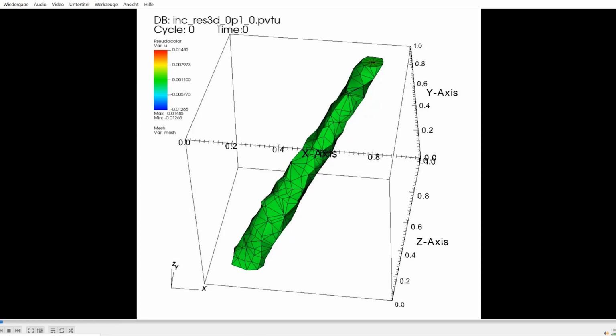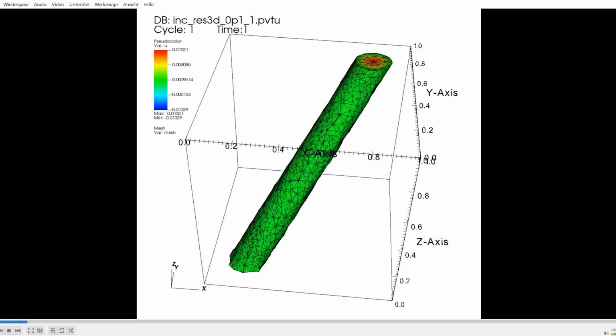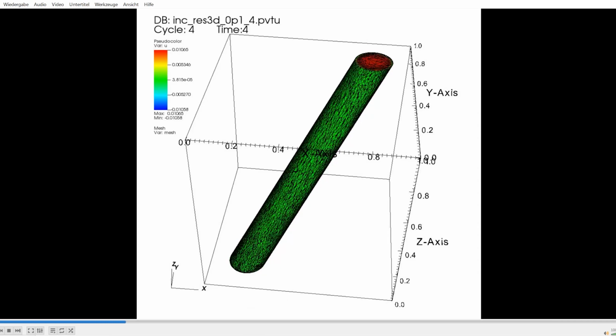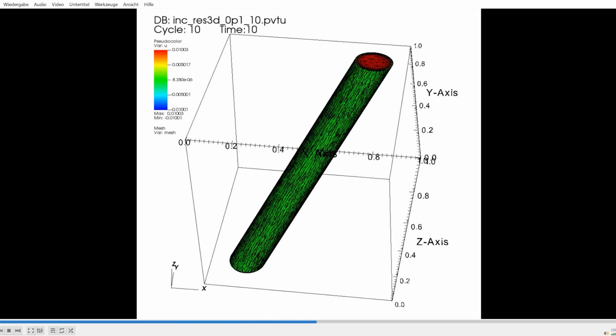It's not good enough, but we still have the shape that will move there, but with not a good accuracy. After that, we perform mesh adaptation on that, rerun the solver, and so on, until here I think it's 20 iterations. And at the end, we have a very good accuracy with a quite good mesh adapted to the solution in space and time. Yeah, I think you can move on, it's not moving so much.